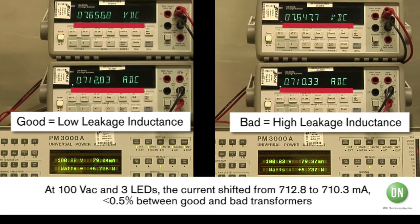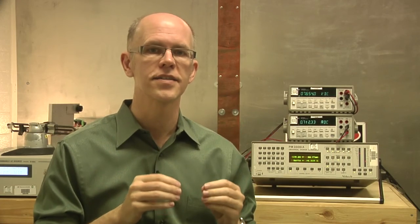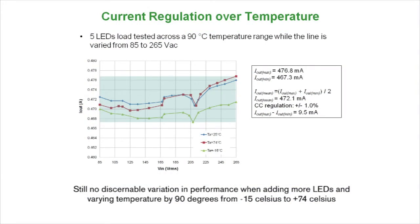We also performed this test using both a good transformer with low leakage inductance and a bad transformer with high leakage inductance. This shows that even with wide transformer manufacturing variation, the current regulation accuracy is very tightly regulated for this solution. We then repeated the test and varied the temperature by 90 degrees from negative 15 Celsius to plus 74 degrees Celsius with no discernible variation in the performance.